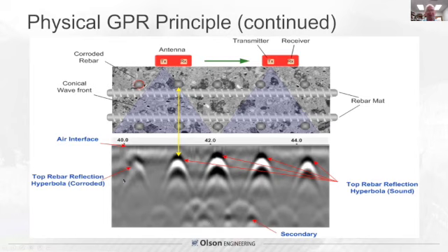So having said that, why is this fuzzy? Well, the presence of de-icing salts and corrosion byproducts and moisture attenuates the signal. So one of the ways that people have used radar to estimate, it's not exactly damage mapping, but it's probability of damage in favorable conditions for corrosion and delaminations, it's a weaker signal, lower amplitude. So that can all be taken out of radar data.